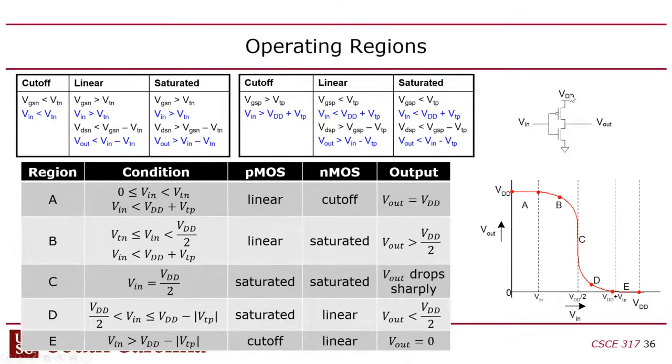So V out and VDD are going to be basically equal or very close to one another, which means the difference between the source and drain voltage is essentially 0. So that Vn is going to look like a real nice, strong value on the gate in terms of the difference between the gate-source versus the drain-source, right? So as a result of that, we're in linear mode. We don't get to cutoff until the gate-source and the drain-source become equal, basically. So that's linear mode, right?